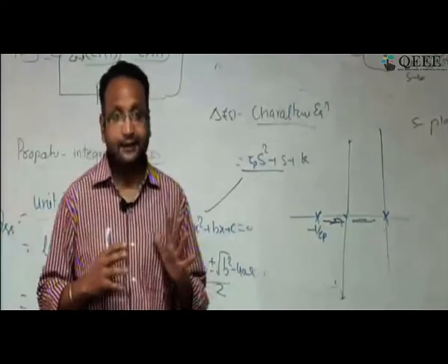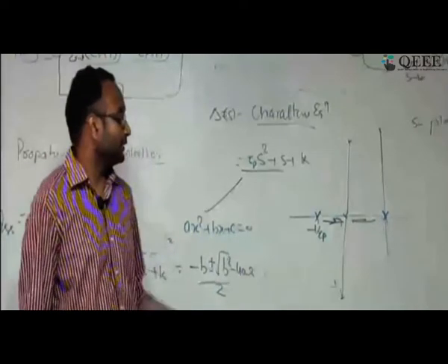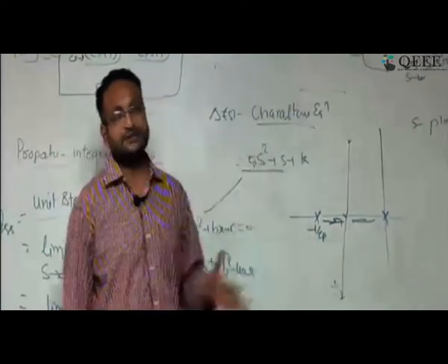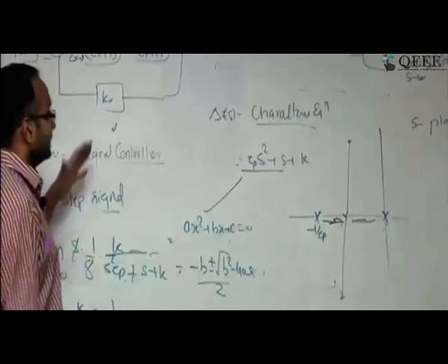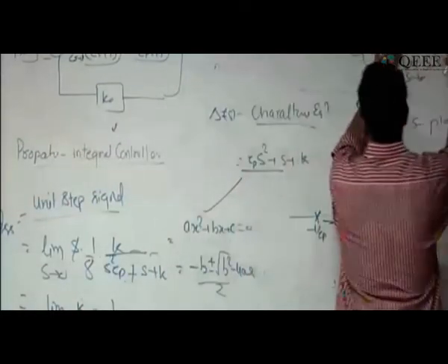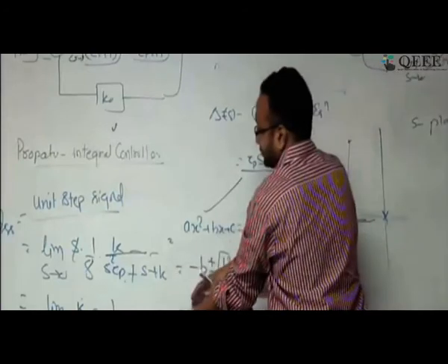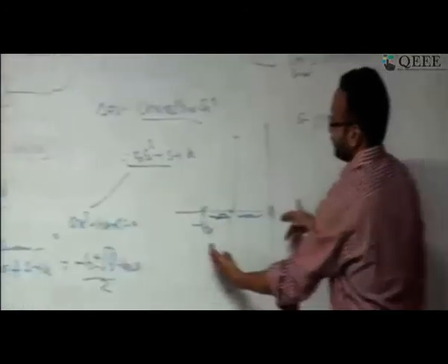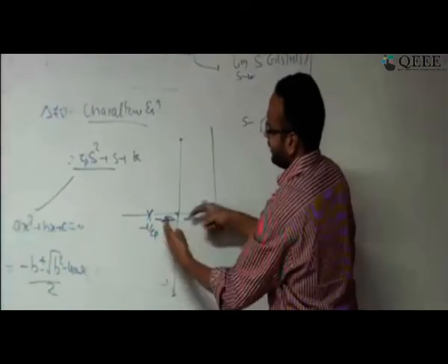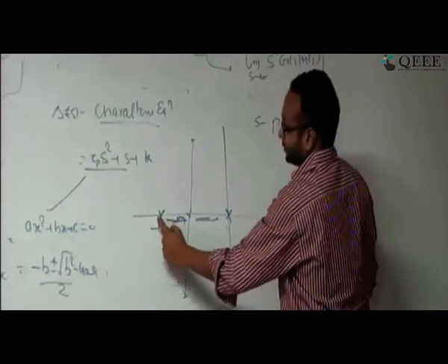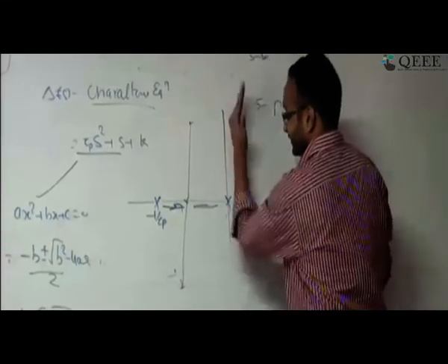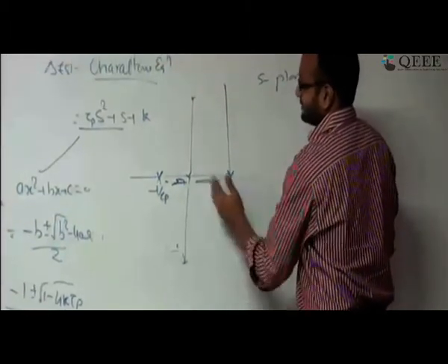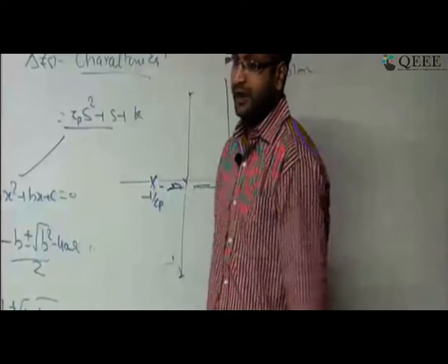This part is clear, that if I use the integral controller, the system is going to be sluggish, but the steady state error is becoming 0. So that's the pros and cons of using the integral controller. And this is the same point I have used in different terms, because it is helping you with the type of the system. In this example, I showed you, look at it. Now I talk about the way roots are behaving, this is called root locus. If you add an integral controller and keep increasing ki, it will force the pole to come towards the imaginary axis. If you come to the imaginary axis, it means the system is becoming slow. That's the point I have explained for both first order system and second order system.